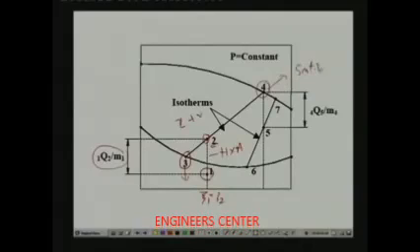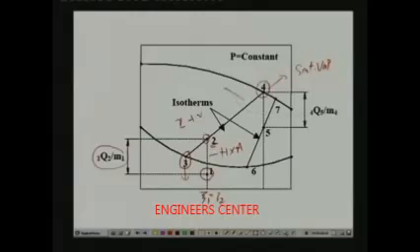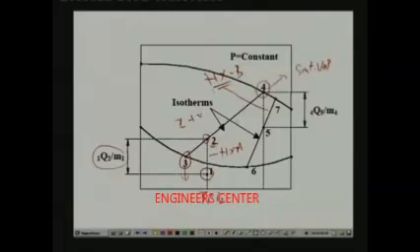From that point onwards, this saturated vapor at condition 4 is cooled in heat exchanger B. So, this is the process in heat exchanger B. Since this is cooled sensibly, by rejecting heat to the surroundings, you find that the exit condition lies at a vertical distance of 4Q5 by M4 below this point. So, you can again easily find this if you know this and if you know this. Similar to this, if you know this you can find this point. So, we have got the point 5.